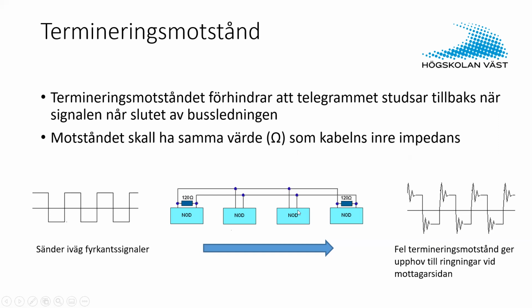The nodes sometimes have a very high impedance, because that's normal for inputs, so they won't disturb the wires at all when you add more nodes. But at the end, the wire shouldn't end in empty space. It should have this resistance at the end.